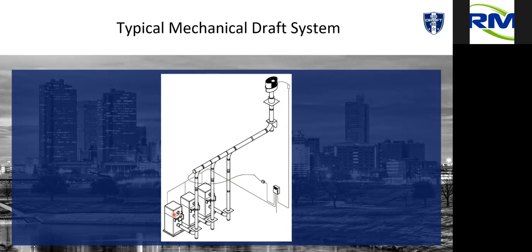Boiler turns back on, comes down to low fire, pressure changes, that fan again modulates up and down. And all we're going to do at that point, from the time we start to the time we are completed, is monitor a certain pressure, whatever that is set in the field, to maintain that pressure in this common. Boilers turn on and off, modulate up and down. All we're going to do is maintain that steady, typically a slight negative.